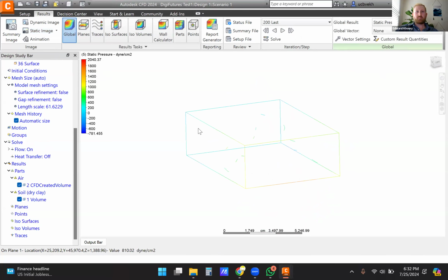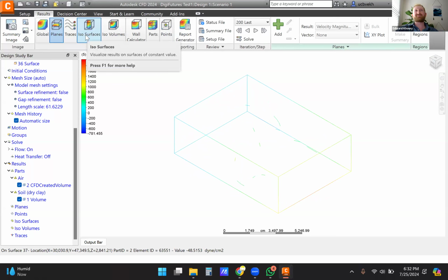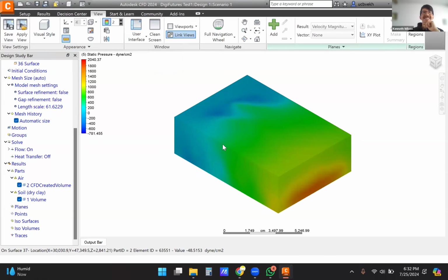It should also be in the legend options, maybe when you right click the legend. I can't tell if it's glitching out on me, but the object disappeared when I added a plane. Okay, cool. That's something you'll notice, that it gets quite glitchy because it's a complex system. So you'll find these random errors and you have to find ways to resolve them. In this case, I just brought it back to shaded and it was visible again.